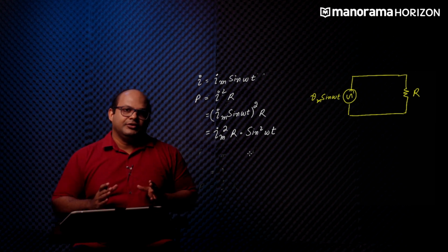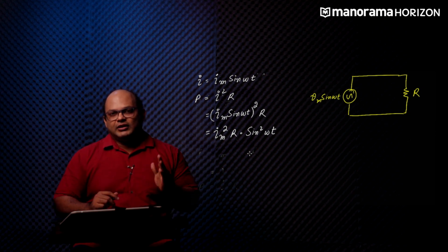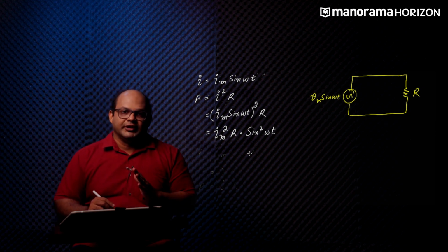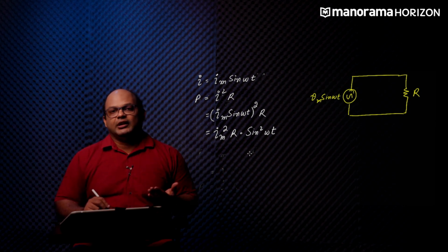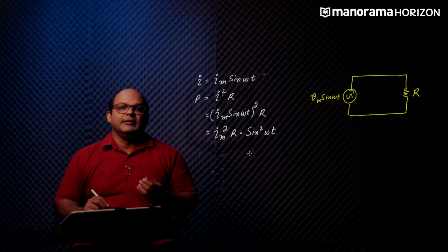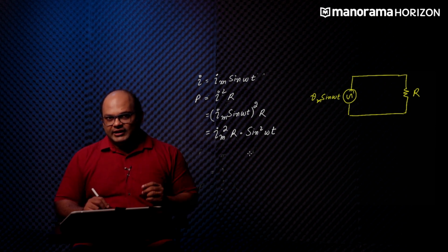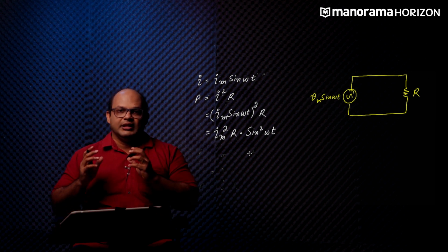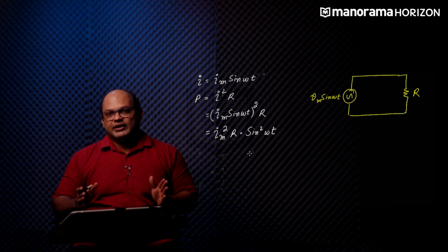On the other hand, it is a different thing with power, because it does not matter what the direction of the current in the circuit is, power will be dissipated in the resistor, because it does not really depend on the direction of the current, but in fact on the magnitude of the square of the current. So by that definition we can come to the power dissipated on average across a cycle for AC power.